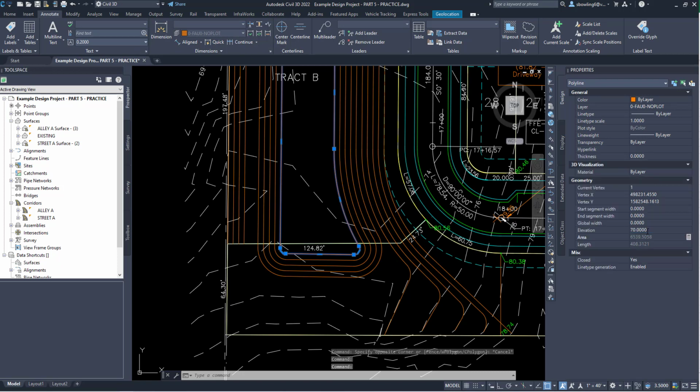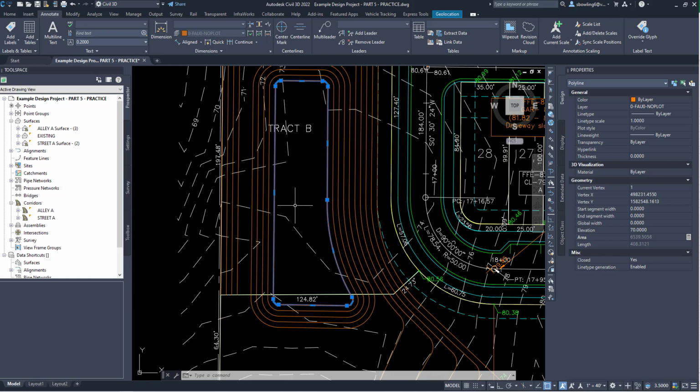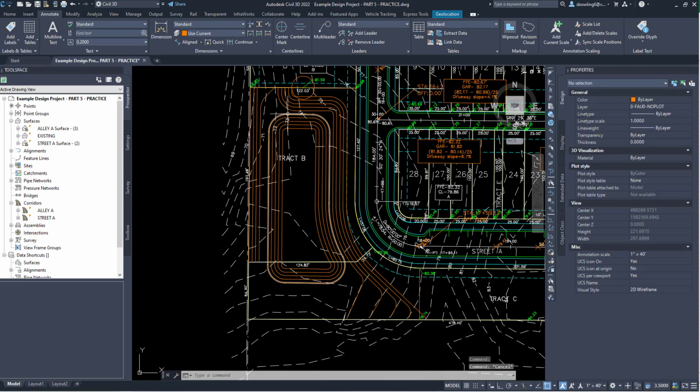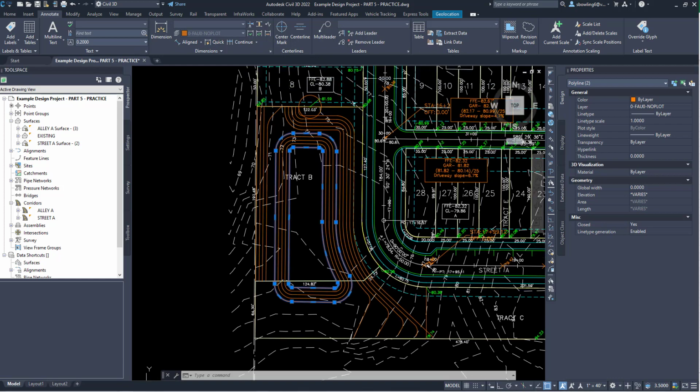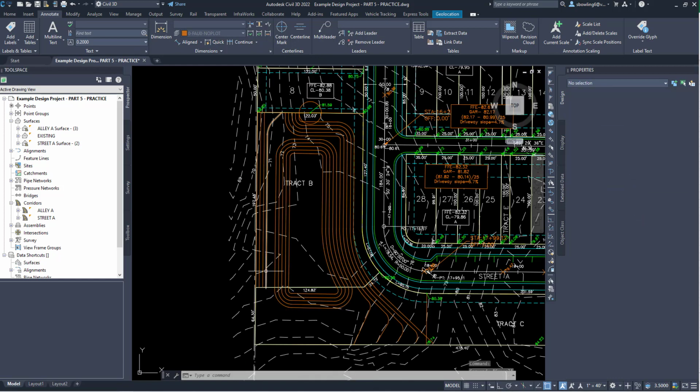When you use a dry pond, you can use a little bit less water quality treatment volume. Now what I have here is from this elevation to this elevation is only our pond area. The remaining elevation is going to be open space. It's going to be just land that we're not going to be able to use.